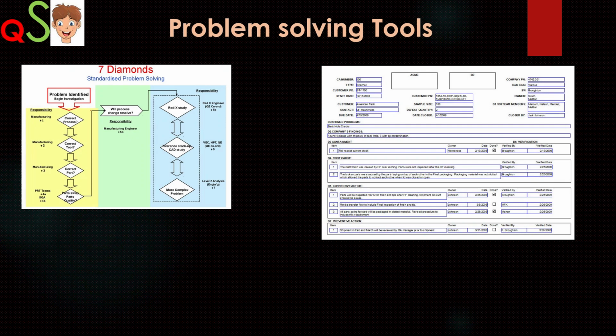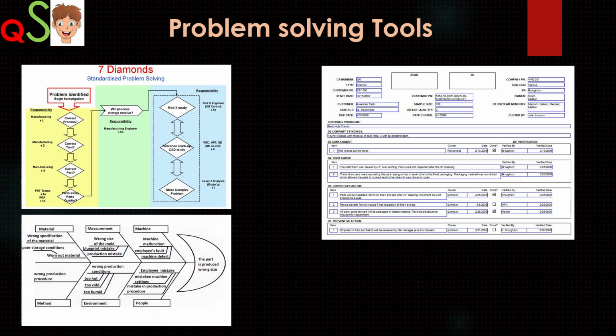If we consider 8D, this tool or method helps you close the problem more comprehensively. I feel the terms used here are much more general and can be used for non-engineering, non-manufacturing businesses also. Ishikawa diagrams help you to know the root cause which led to the problem, defect generation, and misinspection as well, but they do not guide you through the data collection, definition, or closure, etc.